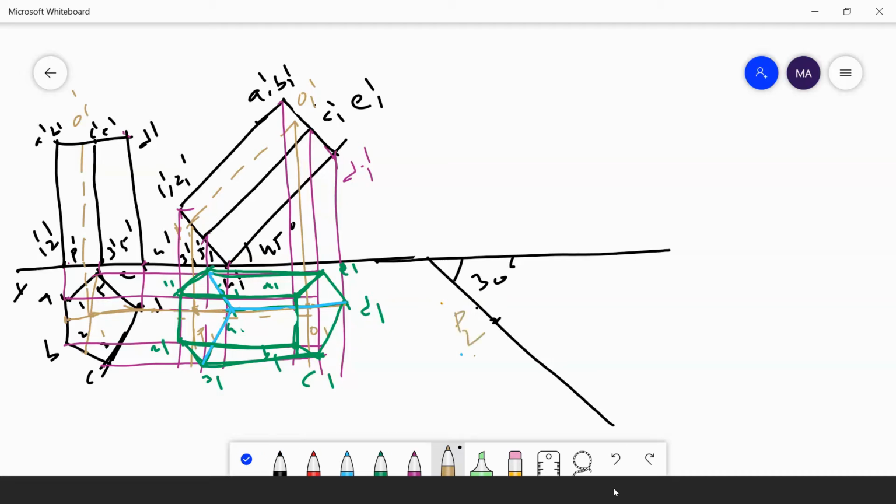I am measuring the true length. What is the given true length here? It is 70 mm. So I am taking P2 as a center and cutting an arc here. Here I will get the O2 point. This one will be the true length. I have cut 70 mm. Then I am drawing one locus from here.